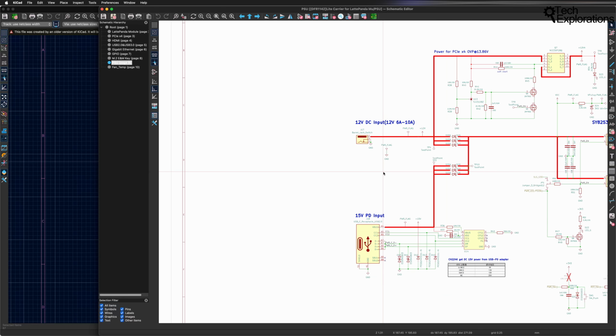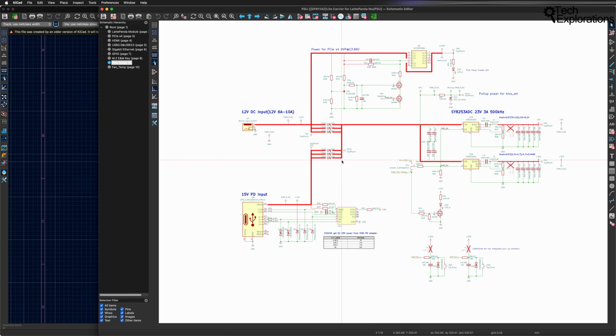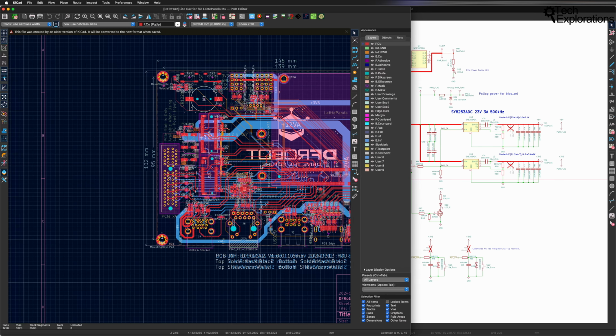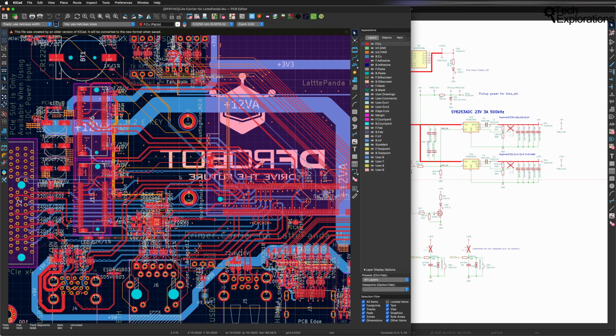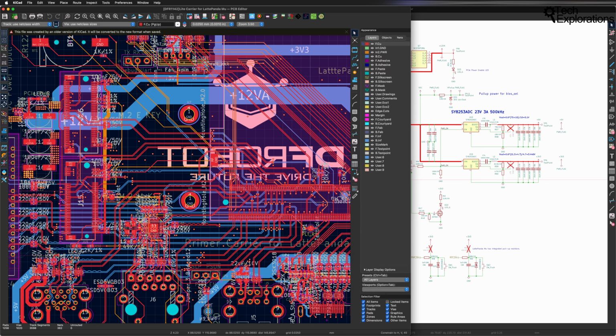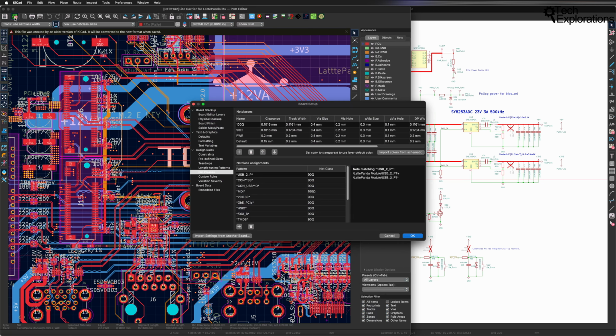And the key insight here is that PCIe requires exactly 12 volts. So rather than adding another switching regulator, they designed the system to accept 12 volts input directly and then distribute it efficiently. Now, if you have a look at the KiCad PCB layout, you can see several high-speed design principles in action. So we've got the layer stack-up architecture. So let's have a look at that.